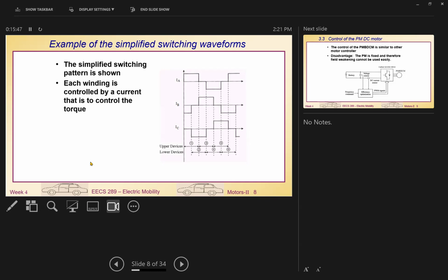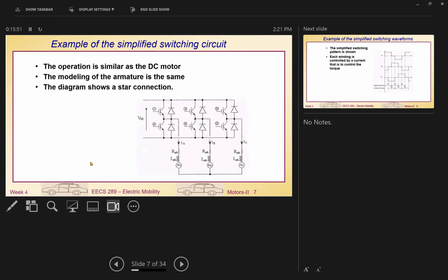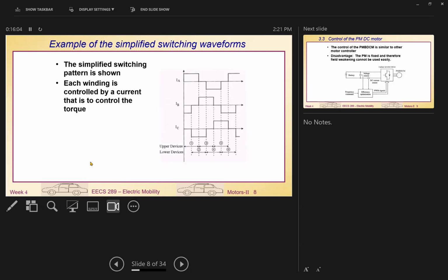There's a special pattern to drive them to rotate the motor. So you can see how we do that, we can label and rotate each of the transistors 1, 3, 5, 2, 4, 6, in this pattern, and then use this special pattern to drive them automatically. Then the motor will have really good forward rotation.